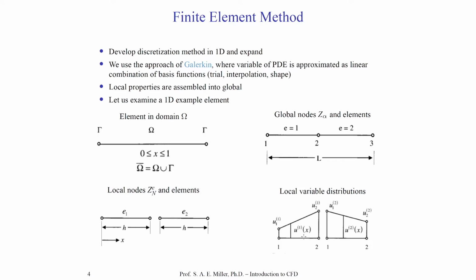So, in a sense, you can already see what we're doing: we've taken the discretization and broken it up into individual elements. Based on the values of the unknown variable at the borders of the element, or boundaries, we can actually construct functions that fit those boundary conditions on an elemental basis. When we go back to the global domain, we would match the elemental interfaces. In this case, element 2 has node 1, which is coincident and should have equal values with, of course, element 1, node 2, right here.